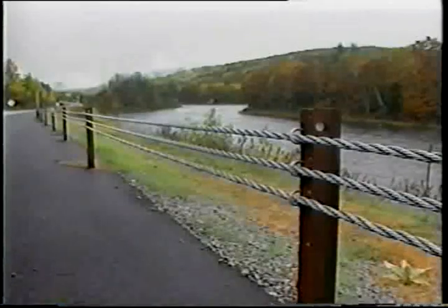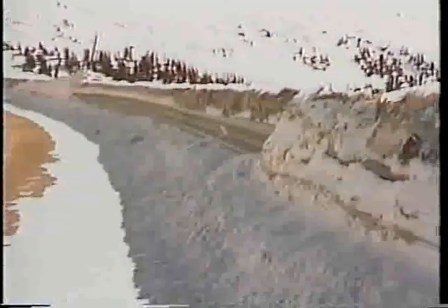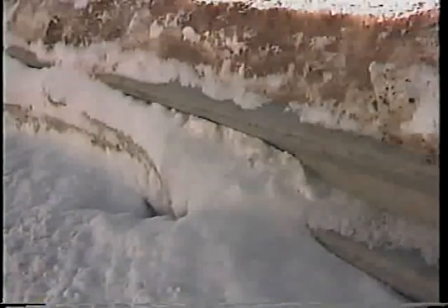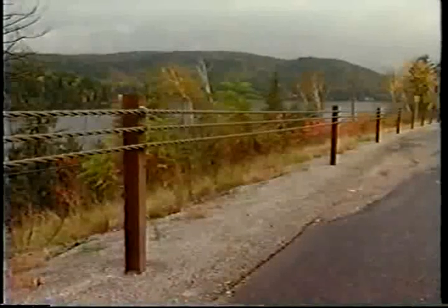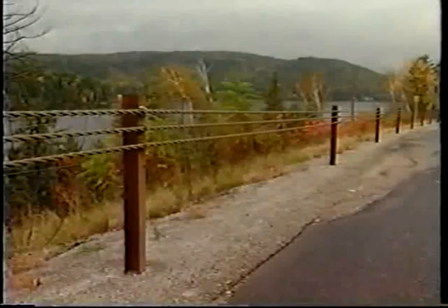Cable systems can be more aesthetically pleasing than typical W-beam or Thrie-beam guardrails, since they do not obstruct the view. The slender cross-section is also an advantage in snowy regions of the country. W and Thrie-beam guardrails can act like snow fences, causing a large pile of snow and ice to accumulate along the barrier. The accumulation from wind-blown snow or snow plowing can prevent the barrier from performing correctly and can also cause snow to drift onto the highway. Cable systems offer very little resistance, so most wind-blown and plowed snow will pass through the cables without accumulating.